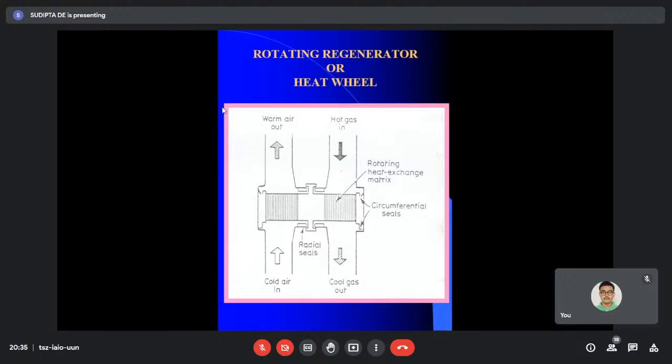For gases, only a reaction in the matrix is possible, so the material has to be chosen such that it doesn't react with the gases in that particular hot gas mixture or cold gas mixture. But if there are carrying dust particles or say acid droplets, etc., then what will happen? These will automatically be deposited, or rather retained, by the matrix during the flow of the corresponding gas.